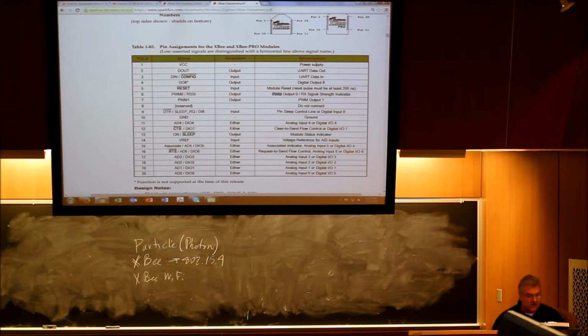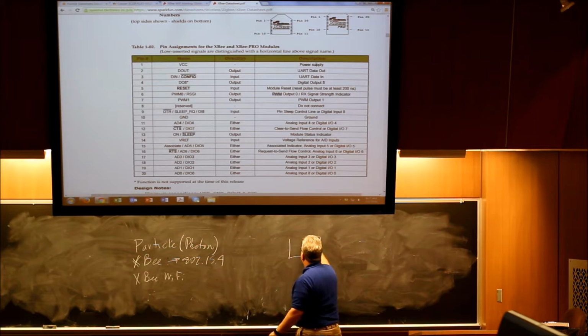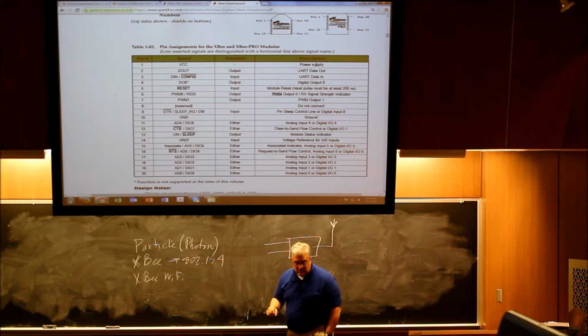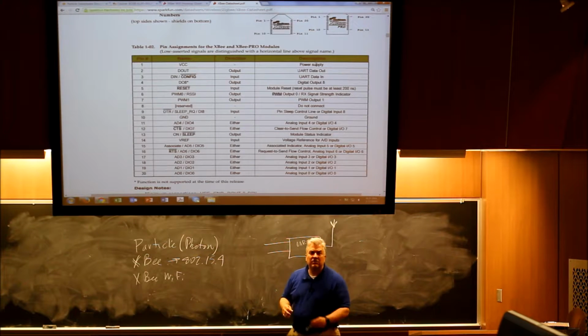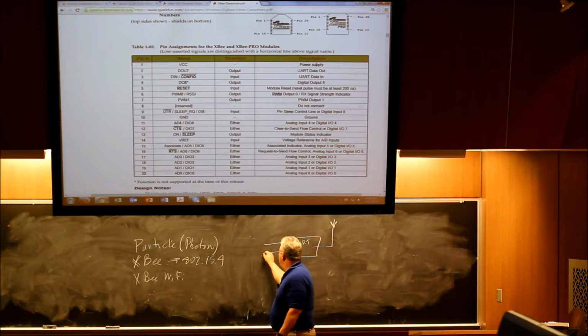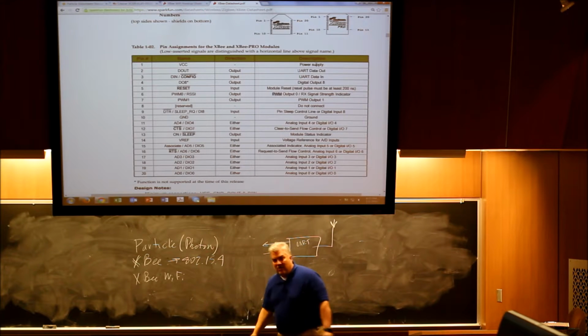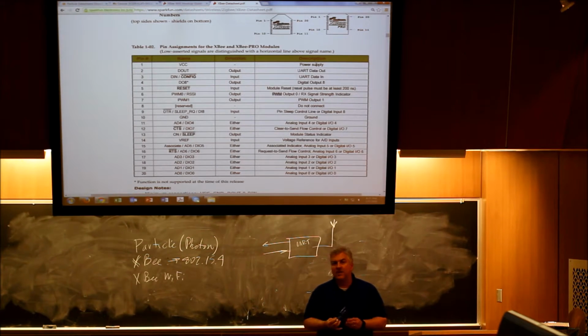So what we're going to see here is a situation where you have your entire device, including its antenna, and you're communicating with it via RS-232. We will have already configured the UART on here to work at a particular speed so that when you send your UART information in and get it out, you know exactly what the speed is, number of data bits, number of stop bits, etc. And that'll be in the lab exercises and the information that Sam is going to make available to you at a later date.